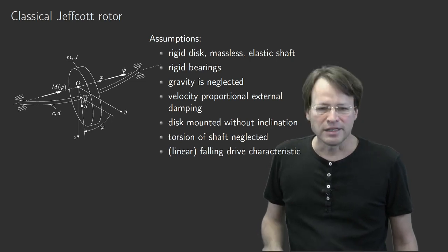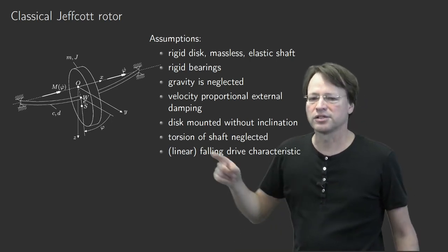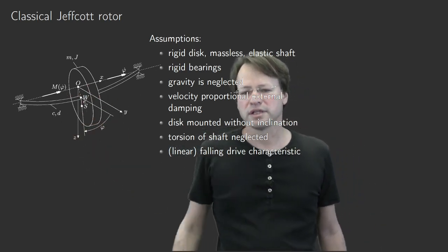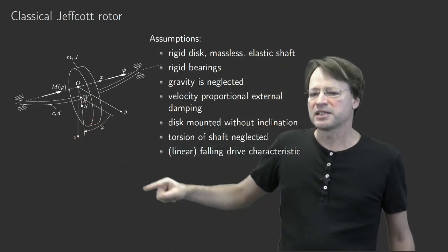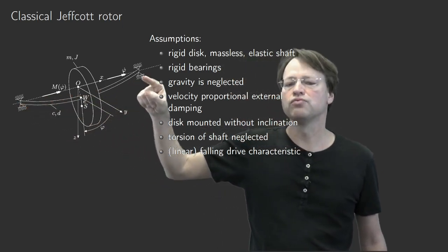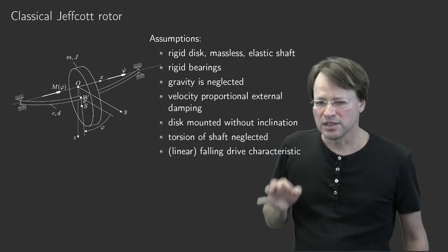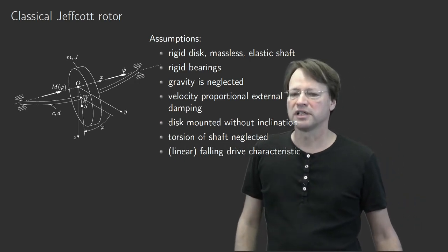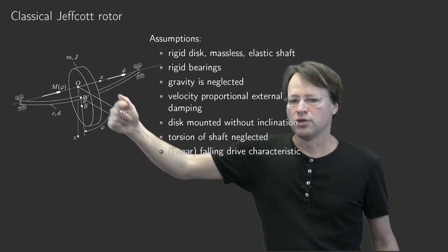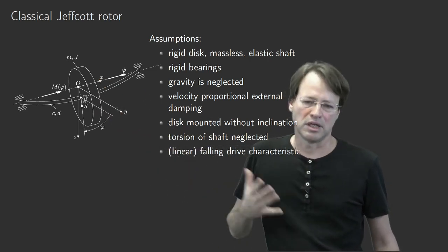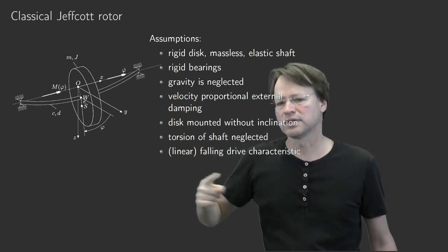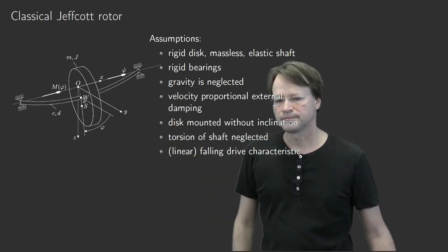First of all, let's have a look at the coordinate system that is introduced here. Where is the origin O of that coordinate system? Can you see it? It's a theoretical line that connects the center of the 2 bearings. This is the origin of the coordinate system, and this coordinate system is an inertia system. Usually the lateral axis is the y-axis, and the vertical axis points downward and is denoted by Z here.